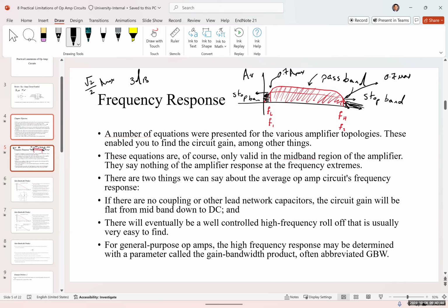So we know that the maximum gain in this system is 20 or -20. Then we slowly increase our frequency on a function generator until the output reaches 14 volts. That would be our upper cutoff frequency. Then I would decrease the frequency until, again, my output voltage reaches 14, and that will be my lower cutoff frequency.